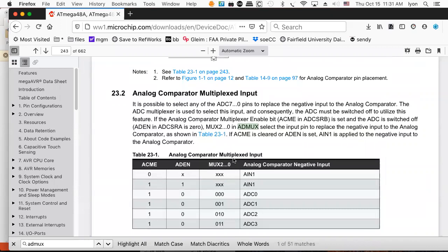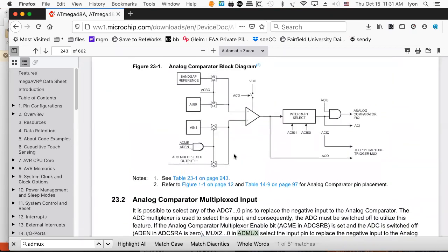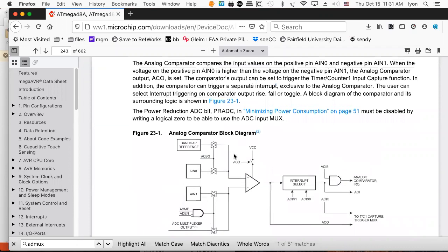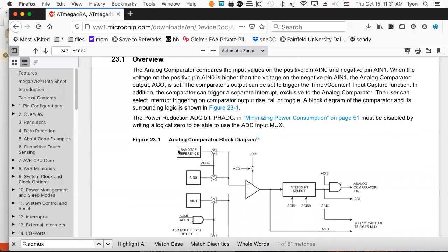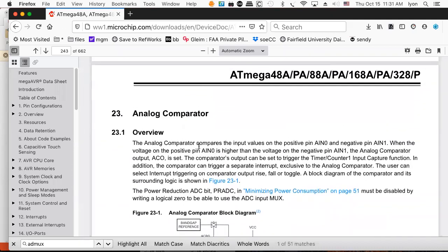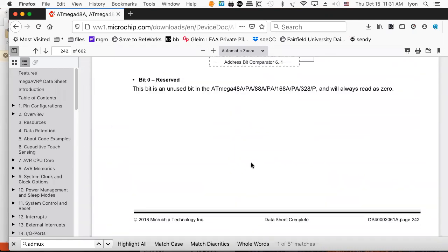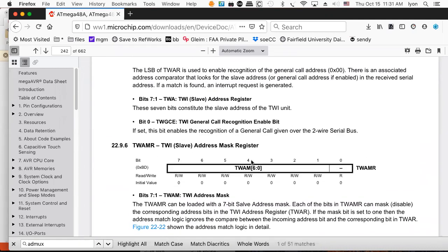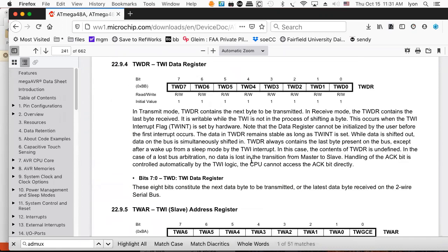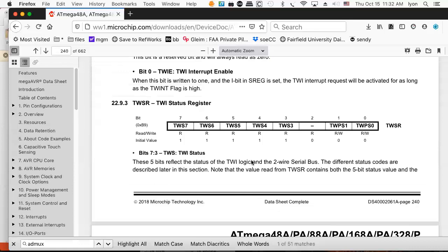If you really want to learn how to use a chip and learn how to program it properly, you've got to read the data sheet. And here's some interesting stuff, this is detail about the bandgap reference that they have. And these little guys in here are analog switches that let you take a bandgap reference and use that relative to an analog input and do a comparator. And there's all kinds of interesting stuff we can do to talk about analog comparators and how that can be used to trigger our ADC converter input. So that's the data sheet. It's there for you to read.